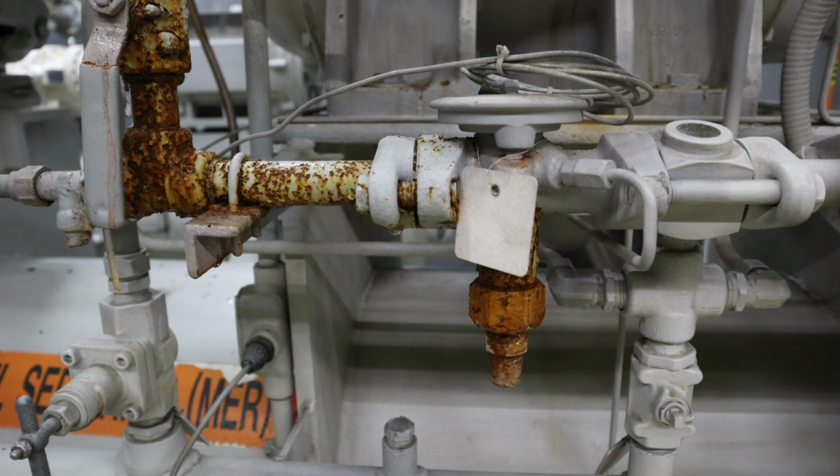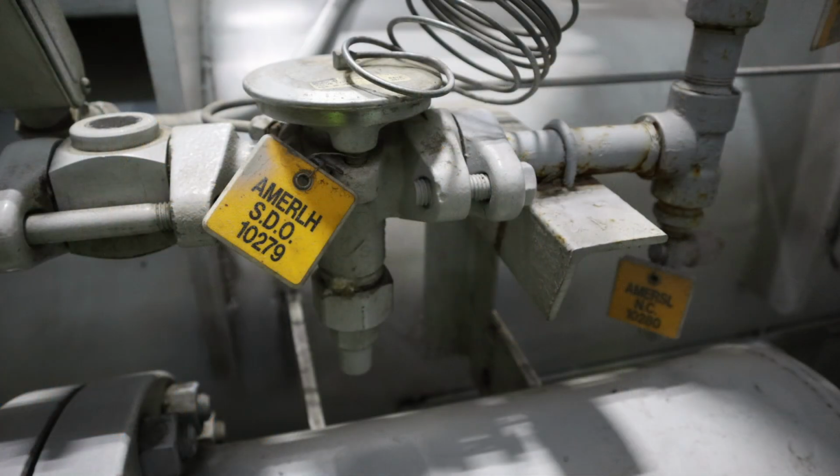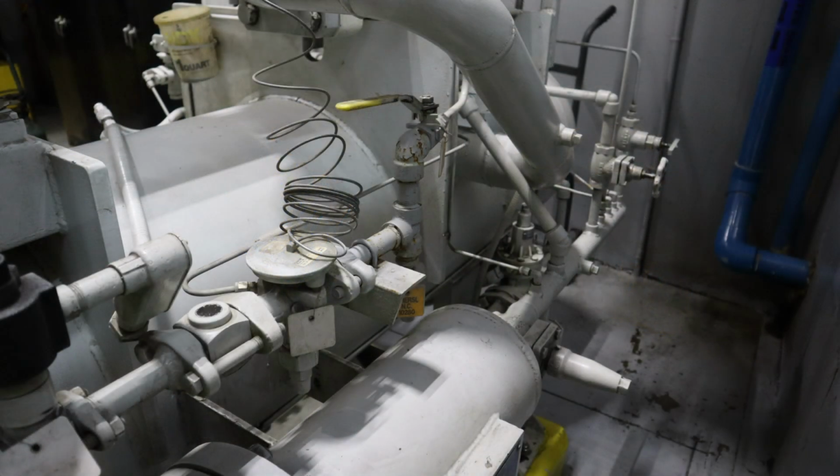The sensing bulb connects to the diaphragm, which when exposed to higher pressures affects the spring mechanism, causing the valve to open and allow more refrigerant flow. Supplying more refrigerant to the evaporator will reduce the superheat and cause the reverse process. Since the refrigerant flows through the evaporator continuously, a TXV provides real-time flow adjustment.